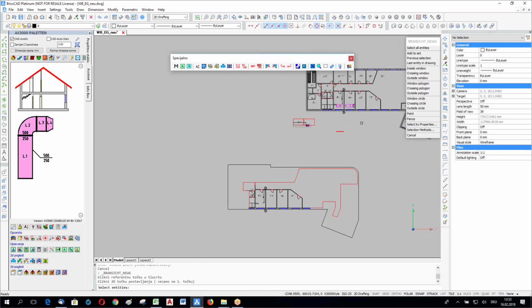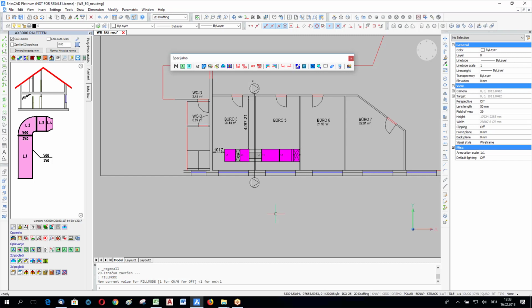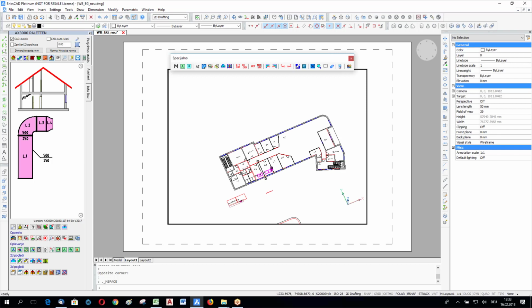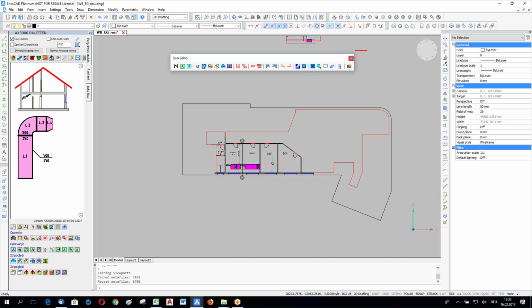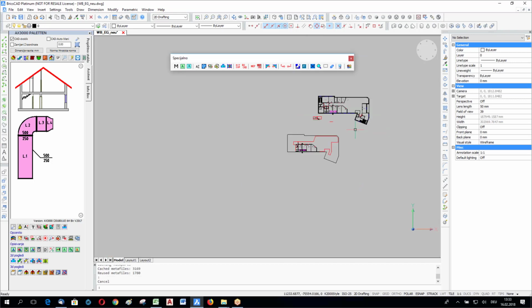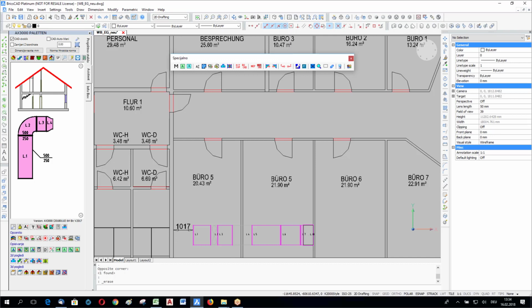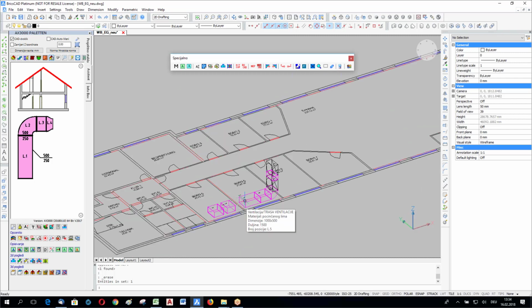And if I select the ducts, the software is drawing a 2D representation inside this plan view. So it's possible in a paper space layout to use one as a 3D view and the other one for 2D fulfilled with hidden lines representation for the ducts. And at the other side, the first icon switches directly the 3D duct into a 2D view. So at the moment you can see the ducts are three-dimensional.